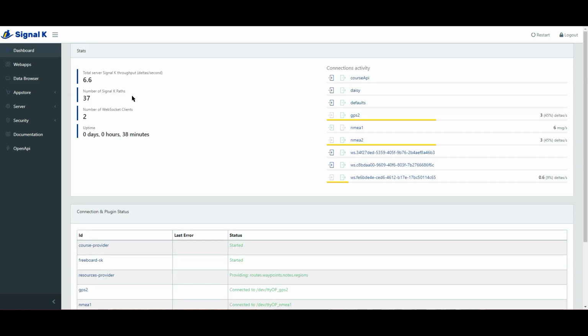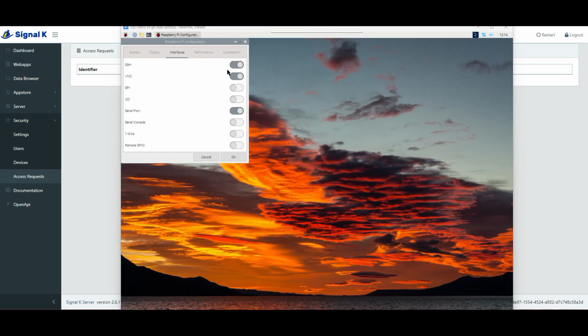Okay, before we dig deeper into Signal K, take a look at the API and the data fiddler and everything, we want to add some additional sensors. So especially I2C is interesting, but we start with a one-wire interface now. And if you want to use I2C and one-wire, you need to enable this in the Raspberry Pi configuration, our Raspberry Config, which we can also access via OpenPlotter.